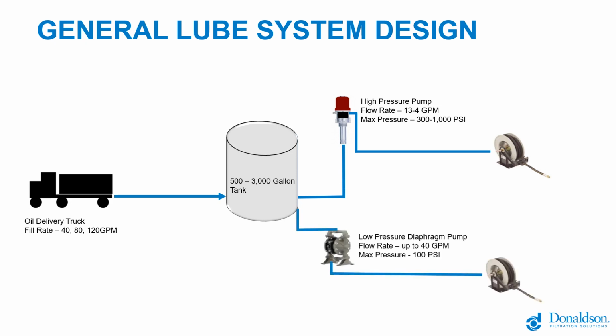You also may have a system pumping at a higher flow rate, say to load out of a bulk tank into a mobile lube delivery truck or a trailer, and that'll run an air-operated diaphragm pump that runs at much lower pressure but higher flow rate to fill totes and other tanks and things like that. So this is a pretty standard system that generically we would encounter, and then we're looking to improve lube cleanliness and maintain it clean as it's being dispensed into equipment.